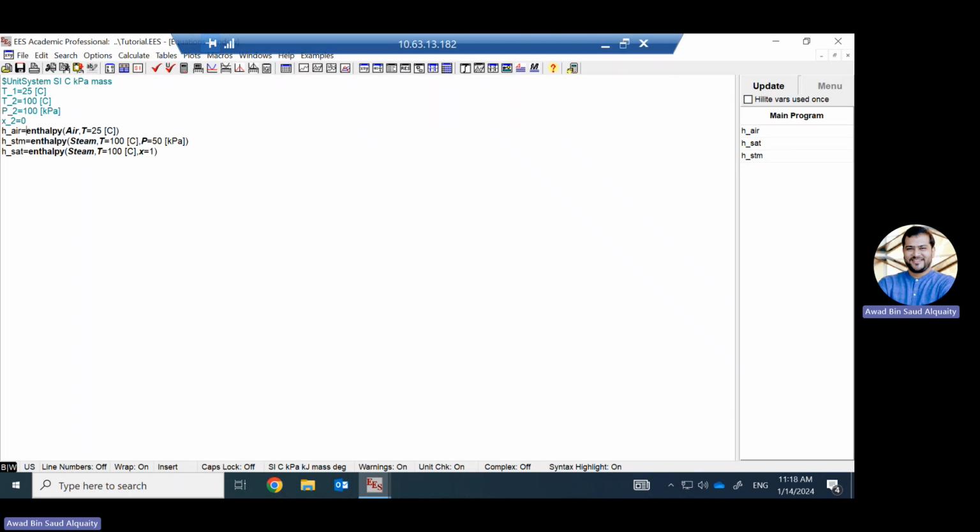So when you go to the function, for example, if I want to get enthalpy of air at a temperature T1, where T1 can be anything, it's 25 here, I can simply write T is equal to T1, and it'll give me the exact same answer. I can, of course, change the temperature there, and I don't have to come back and change everything again on the function itself.